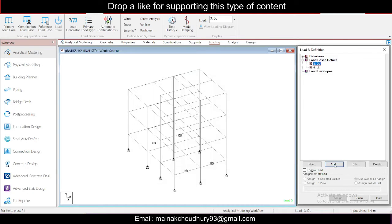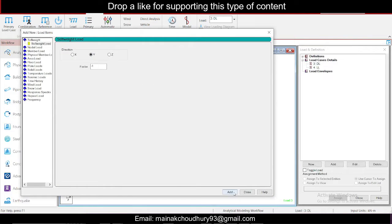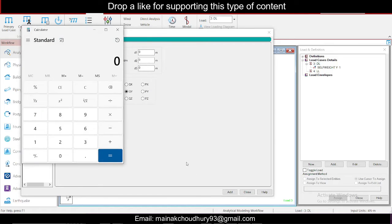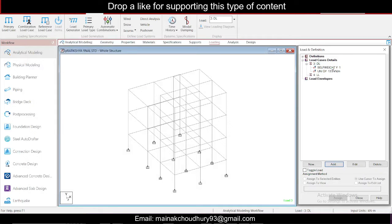So simply for the dead load, let's add the possible dead loads here. The self weight will obviously be there, and the member load. Now for the member load we'll calculate this. The building height is 3 meters. Deducting the beam, let's take 2.7 meters, into thickness of the wall, into unit weight, let's consider 20, so it is coming as 13.5, so minus 13.5, and click on add and close this.